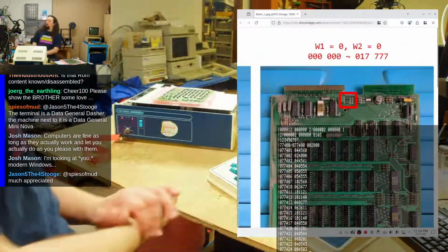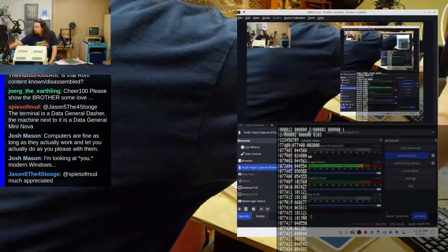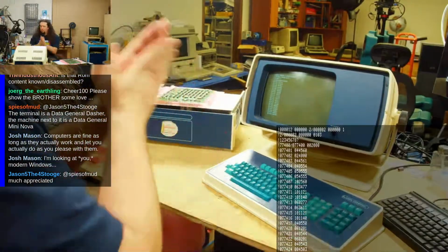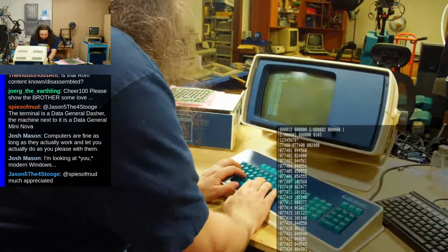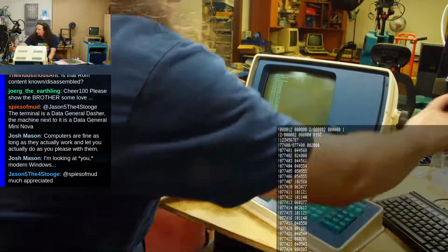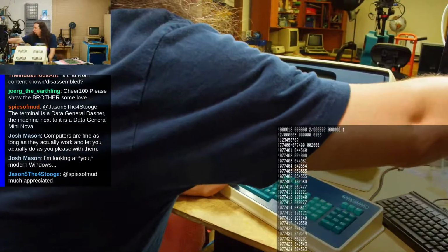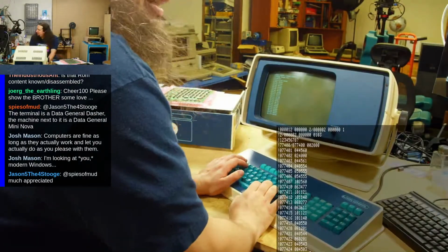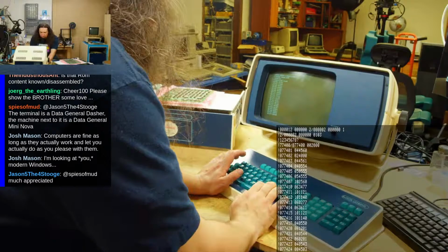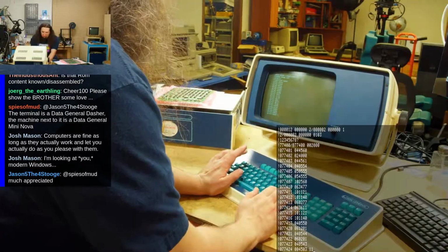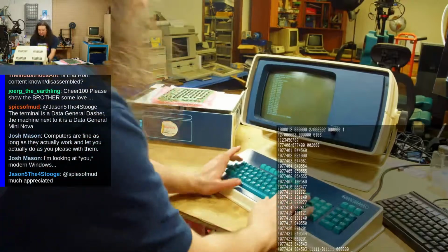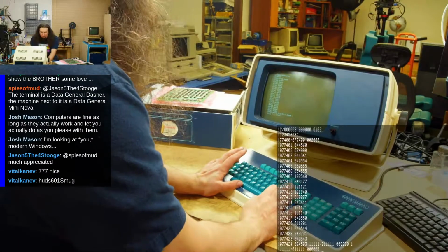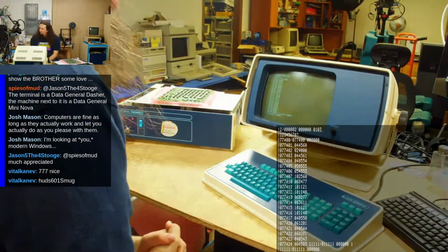With the ROM range I showed you, it should be possible to write memory pretty much anywhere else, but we can't. Let me give you an example. Let's look at card 1. It should go up to memory address 17,777, so let's use memory address 11111. We should be able to set this. I'm going to attempt to set that to 1, then look at it again. That is 5 ones, and it's still set to 0. This is the issue we're having.